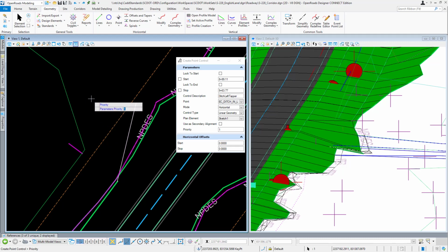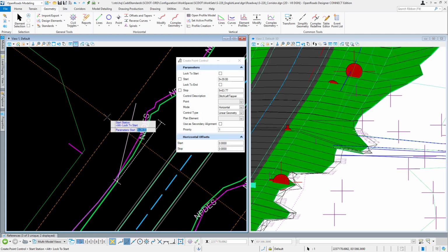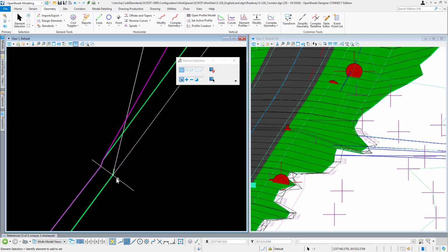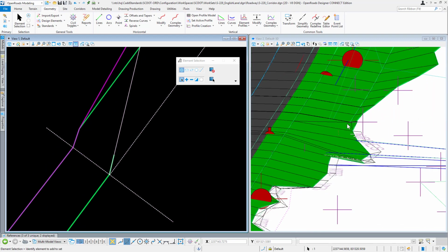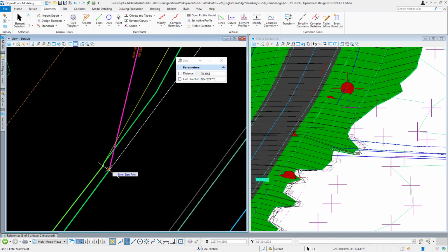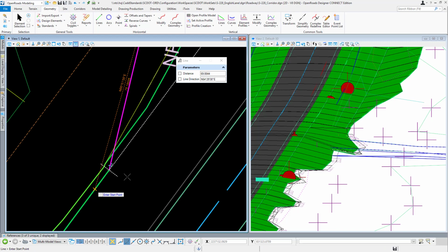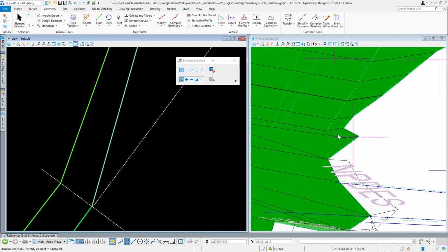And again, we can go back and change these later in the corridor objects dialog. And then we can also again do tapers. I'm just going to do 0 and 0 to keep it simple. And then it grabbed it. There we can see it solving that a little bit. One of the reasons I snapped to that line is we can come here and move that further down and it'll solve that ditch dynamically.